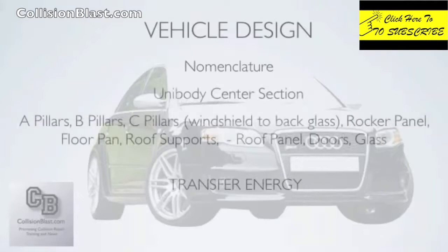Now we've got the center section, and this is your A pillar or windshield pillar, your B and C pillars, and basically, like I said, it's from the windshield to back glass. That is your passenger compartment. It also consists of the rocker panels, that's below the doors, the floor pan and the roof supports, and then you've got your roof panel, your doors, and your glass. That is basically all of your center section.